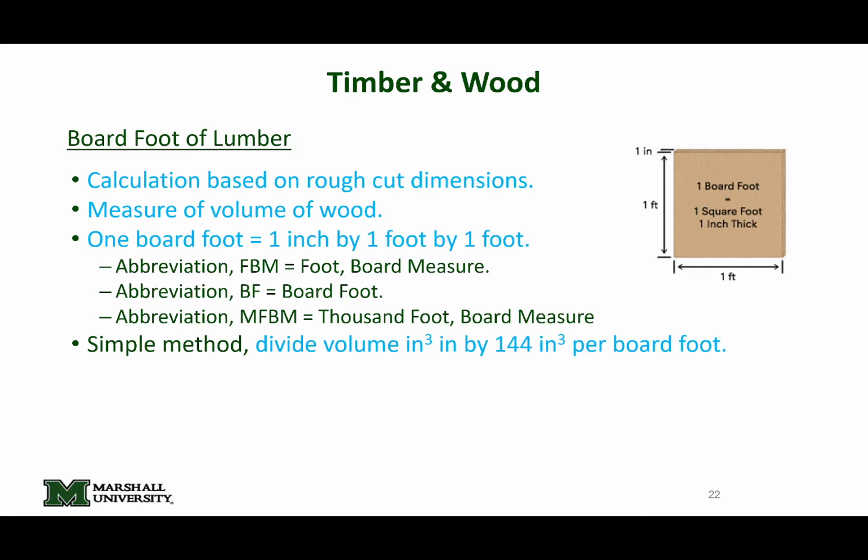This basically applies to plywood. So if you were trying to figure out the amount of board feet in a 4 foot by 8 foot sheet of plywood that's 3/4 inch thick, don't use 3/4 of an inch, just use 1 inch. Again, this is a cost estimation tool for the purposes of getting a dollar figure on it.